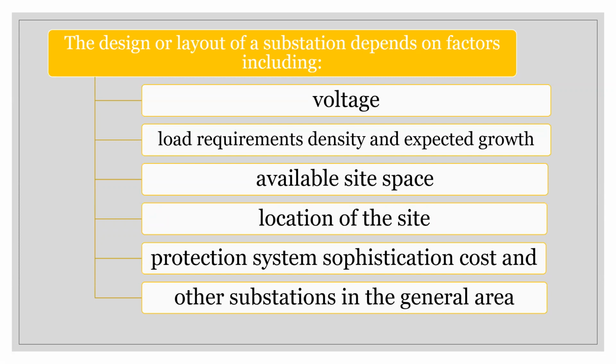The voltage level would speak to things like clearances. And we'll speak about that in a little more detail in a few minutes. So the design or the layout will be dependent on your voltage, the load requirements in terms of the density and the expected growth. Also the importance of the load.